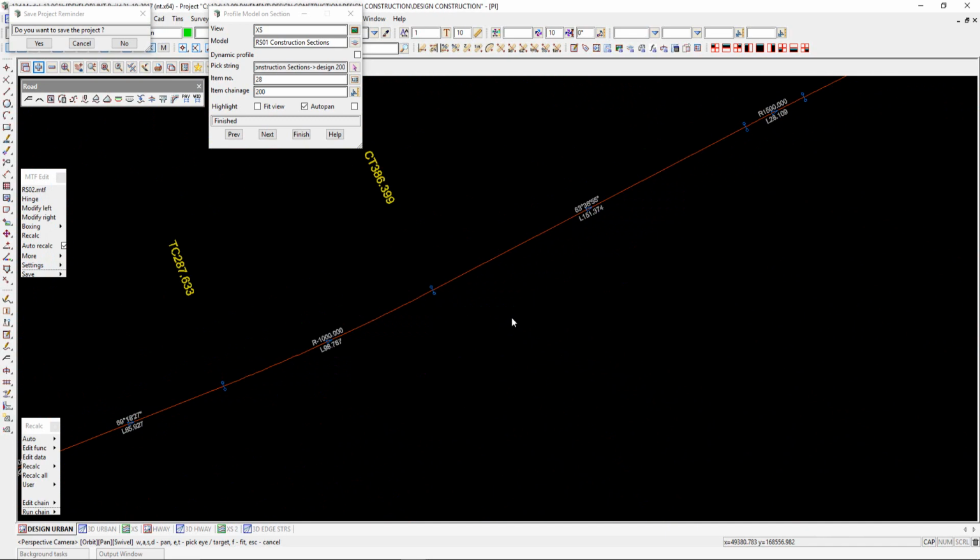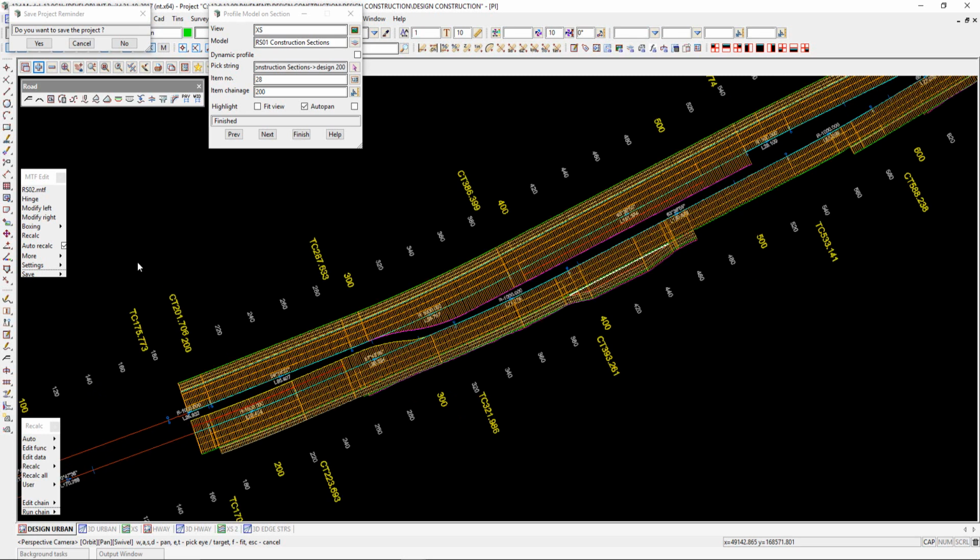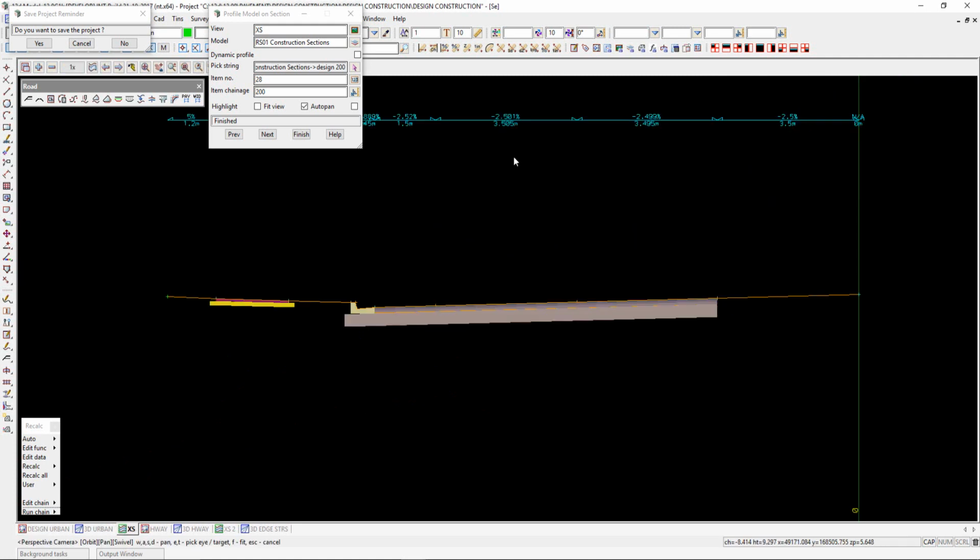So in the Design MTF file, as we've seen in the other road, we can run the snippet and pick strings and produce the pavement profile. There is another way of doing it. If I just save and finish that, and look at the other road, this particular snippet worked well on my road, picking one string here and one string there, because there was a constant crossfall.